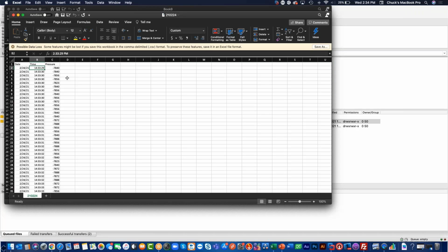If you'll notice here, here's my timestamp, and that's at 14:33 and 29 seconds. And I only got one sample in during that second, and then I switched over to 30 seconds. And let's see how many samples I got in the 30th second. 1, 2, 3, 4, 5, 6, 7, 8, 9, 10. Yep, sure enough. So I got 10 samples within every 1 second.